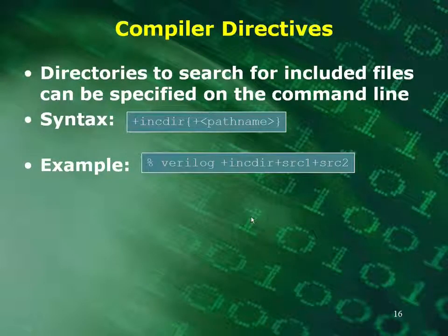Directories to search for included files can be specified on the command line, and you use the +incdir with one or more +path names. So here's an example. Verilog, your +include directories, plus whatever other source directories you might want to add. That's an example.